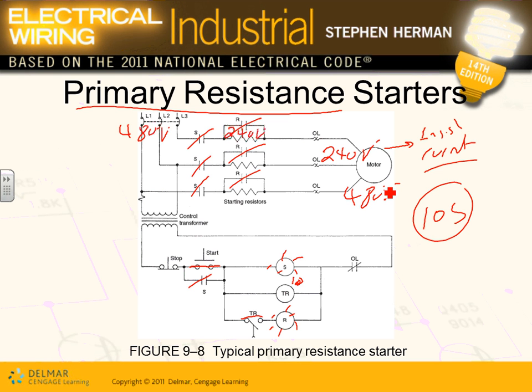By reducing the voltage, you reduce the inrush. Who cares? What's the inrush? The current. The question always is, who cares? That will reduce, your light will not dim, your circuit breaker will not trip. Your mechanical equipment, if you're a conveyor, imagine a conveyor and you crank the motor and the motor, bam, pulls everything else. It's going to jerk the machines, right? What happens if you keep jerking a machine? It'll bust it. So by doing it this way, they reduce the mechanical and electrical impact on the motor. That's called voltage reduction at the start. This is not speed control, it's voltage reduction.